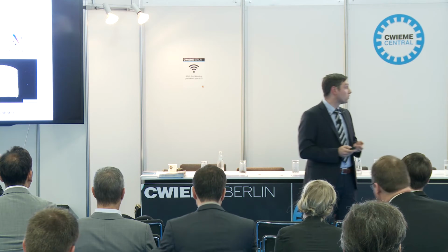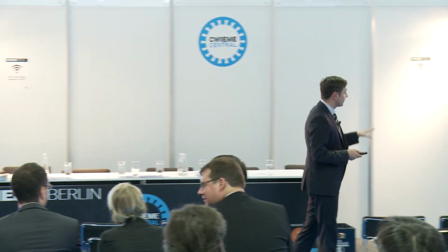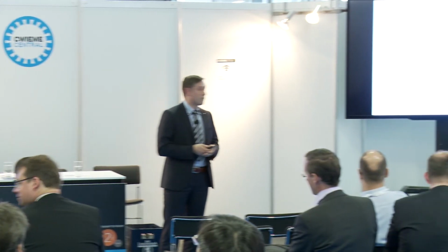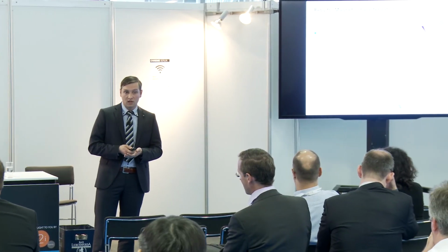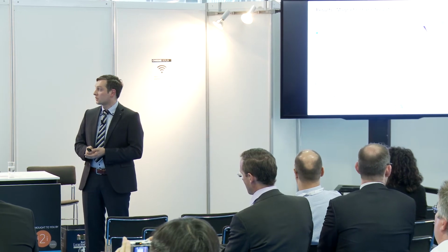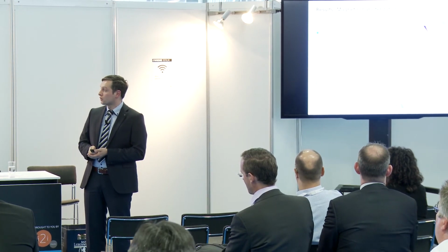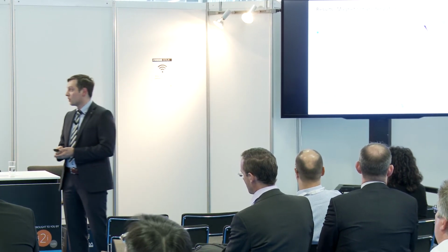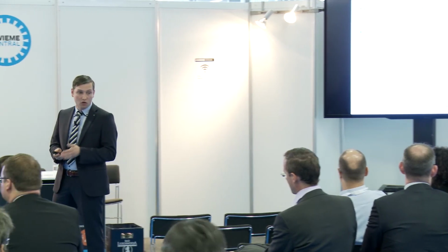And the same holds for the magnetic properties. Here on the left-hand side, I've shown various manufacturing techniques. The black line represents the annealed state. And laser remote cutting achieves a very good magnetization behavior, followed by the guillotine and conventional laser cutting, regardless of the chosen laser beam source, gas laser or solid state laser.